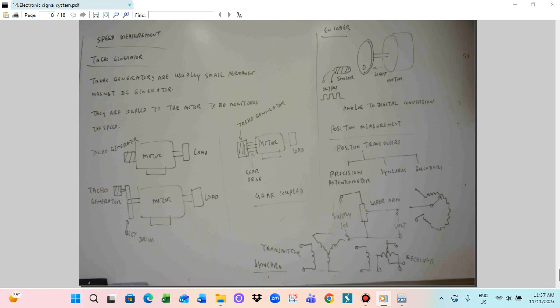You can see on the left side, the middle and right one is the three-phase induction motor, and the middle one is the two windings of the generator. This is a three-winding armature winding, but the left one is a permanent magnet. This permanent magnet can be used as a tacho generator or the PM exciter. Later we will study the characteristics of the PM exciter. Excitation will be given to the supply and we can study what happens, and the rated speed and the generator voltage will be measured. Tacho generators are utilized especially for speed measurement.